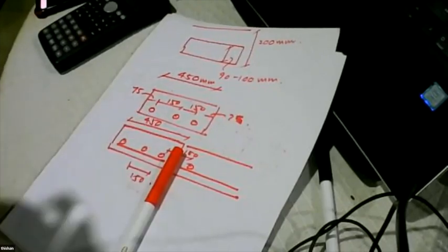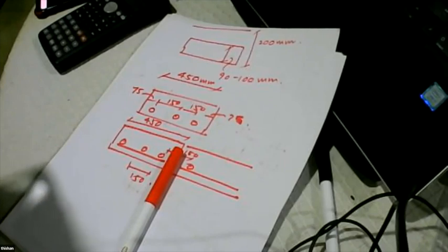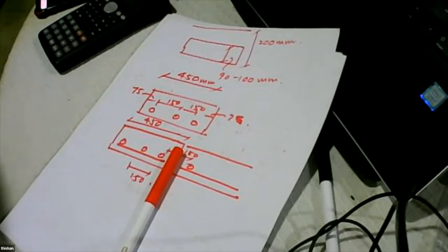So you have to be a little careful. If you select a 2 meter spacing for the longitudinal beam, sometimes you will find that beams are also too much loaded. Because of that reason, the general rule is we try to keep about 2 beams per lane. Altogether 3 beams supporting a lane.